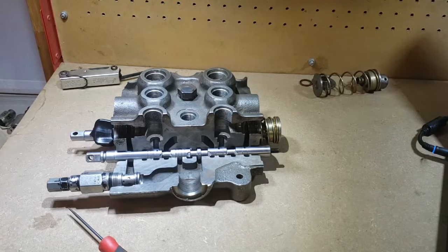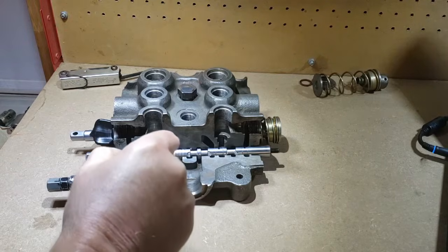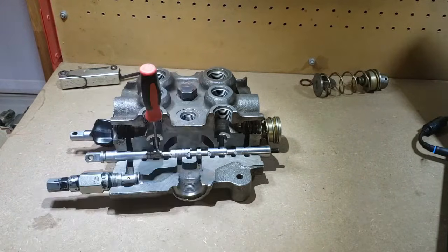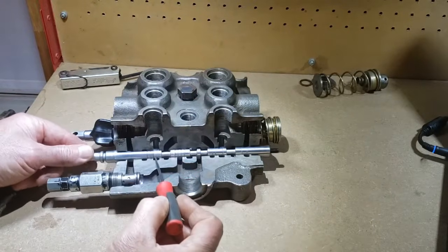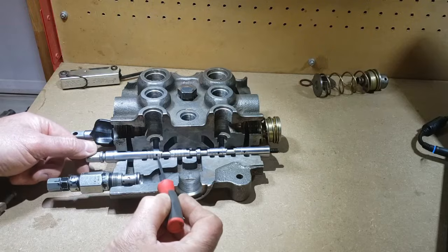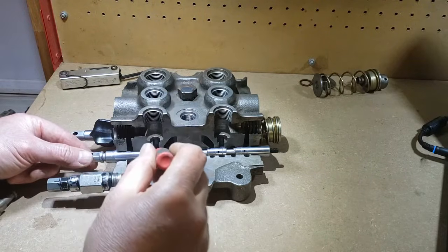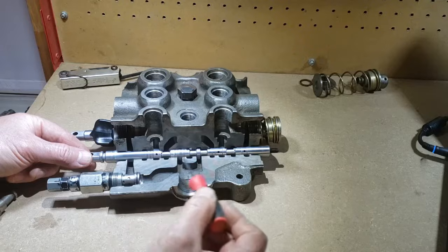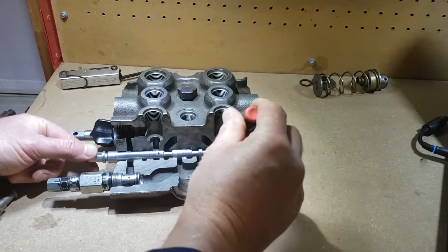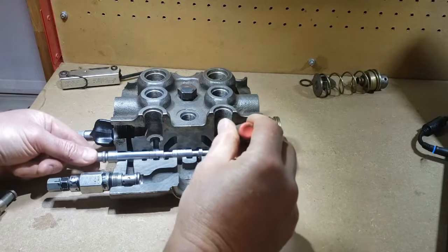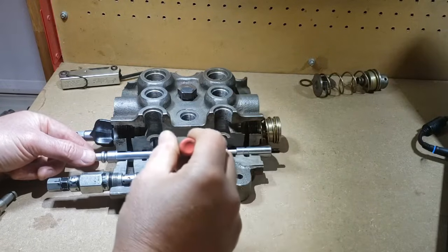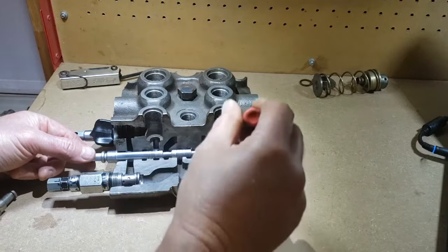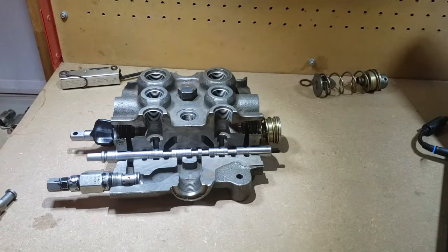And in float, that's where these holes come in. You'll notice there's holes drilled into the center of the spool. One set of holes around the valve radially. There's 1, 2, 3 holes drilled around it radially. They connect this work port into the center of the hollow spool. Then I've got another set of 3 holes drilled radially in at this work port. And because the spool is hollow, what we've effectively done in this position is connect the 2 work ports together. So head and rod end are connected together.